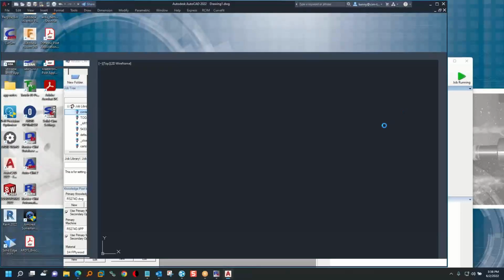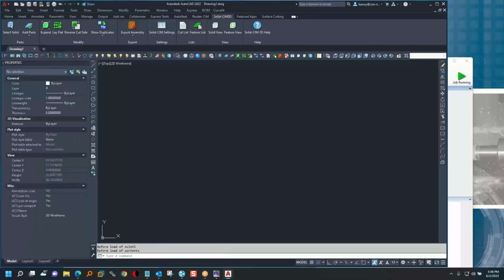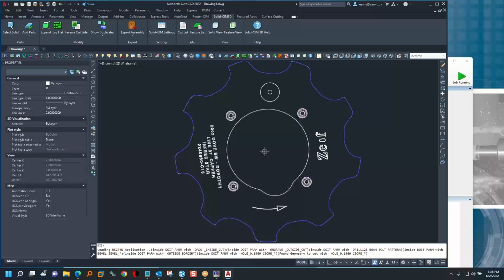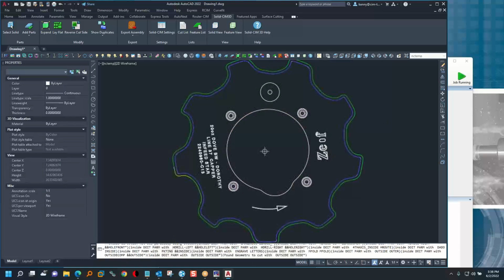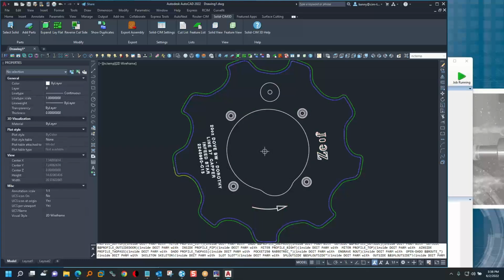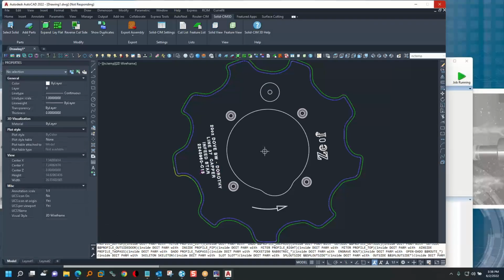So we run that now. That's what it does. It flips it over. You put the sheet on the table upside down, and it does all the backside operations and trims the edge of the sheet. So when you flip it over, it's a trimmed edge. It goes back up against the pins, and then it does the front side. And I think I also have this set for stay down nesting, so the 2 pieces will be connected together with the stay down operation.